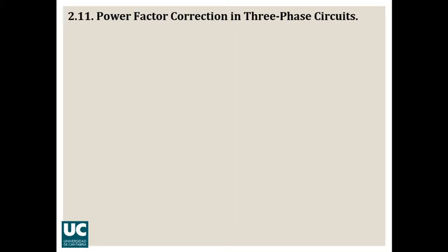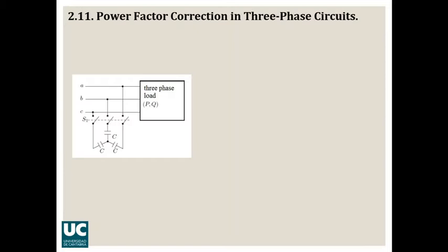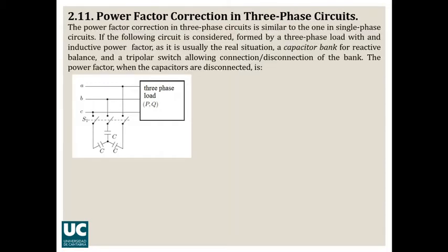Hi everyone. In this section we are in 2.11 Power Factor Correction in Three-Phase Circuits. Here you can see a three-phase load which is connected to a three-phase circuit, and you also can see a bank of capacitors which are connected in a star. So the power factor correction in the case of three-phase circuits is quite similar to the one we have already seen in single-phase circuits.